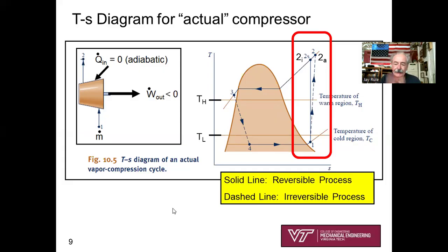And so I hope looking at the sketch of the compressor process gives you a pretty good idea of how would I do the analysis for the compressor part of this refrigeration cycle. This is what your sketch should look like for the adiabatic and irreversible situation. You should see both of these lines, both the solid line for the isentropic, which you must study anyway, the dashed line for the irreversible adiabatic situation.